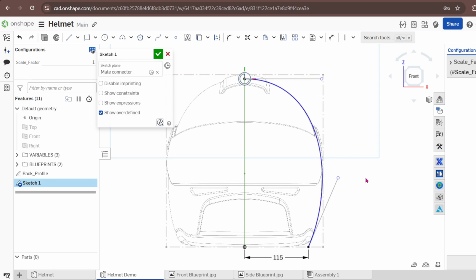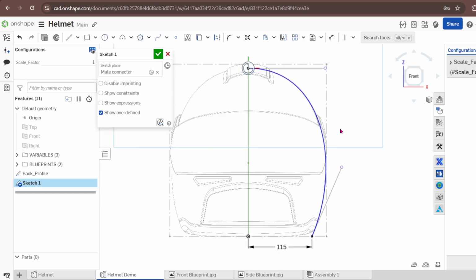One tip about spline, do not dimension them before tracing the sketch or your blueprints. Do not dimension after. You can see I've done that, then I can dimension them. It becomes the last step. This is on that 8, I can make it 140.